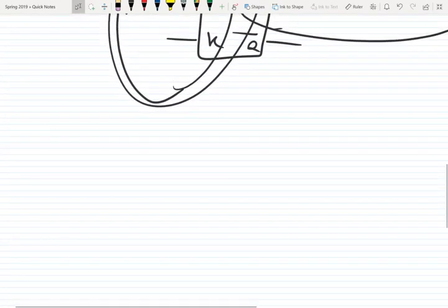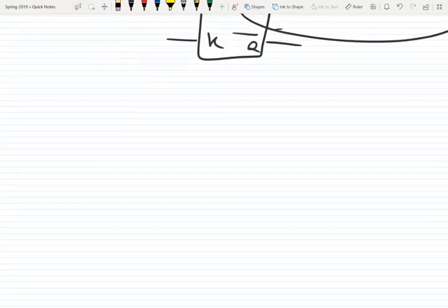By the way, it's a question. Why do we need to know the characteristic excitation table during the design process? When we design a circuit, we usually know the transitions from different states, and we want to design the inputs. So outputs are known. We know the transition in the circuit, and we are supposed to find the inputs.